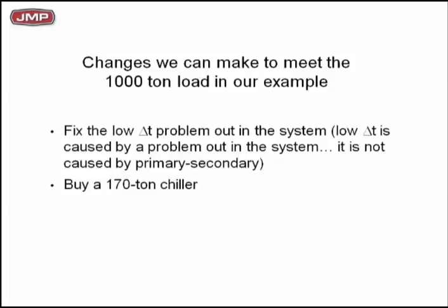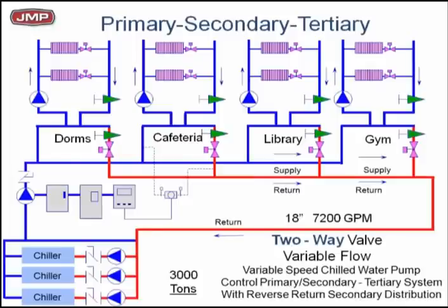I cannot repeat that enough. Get that idea in your mind. When you look at systems, think in terms of what the return chilled water temperature should be. You've got variable flow and two-way valves. It should be at design or higher. So where are we going with all this? When you look at primary-secondary systems, you need to understand the impact of varying the flow and two-way valves. You need to understand the impact of not having design return chilled water temperatures.